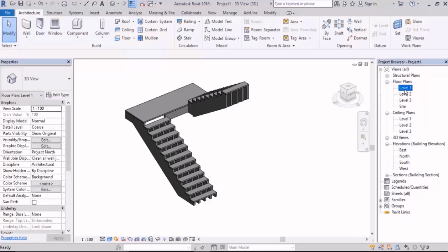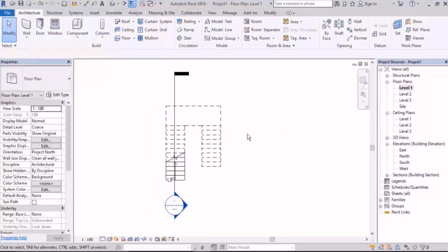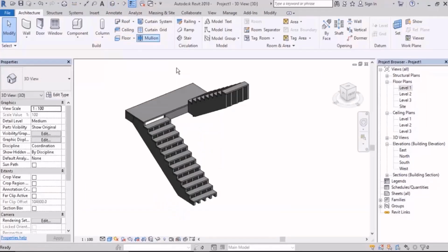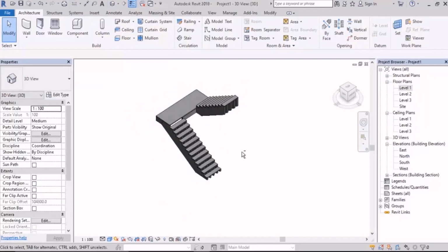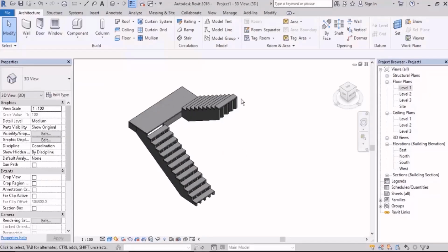You need to control those things and also check the number of the stairs. You see how much I insist on it? Now for this staircase, when it was designed, it had 20 stairs and it was correct. But now the desired number of the risers or the stairs is 23. So the result is that the stair that was correct has not reached the level.